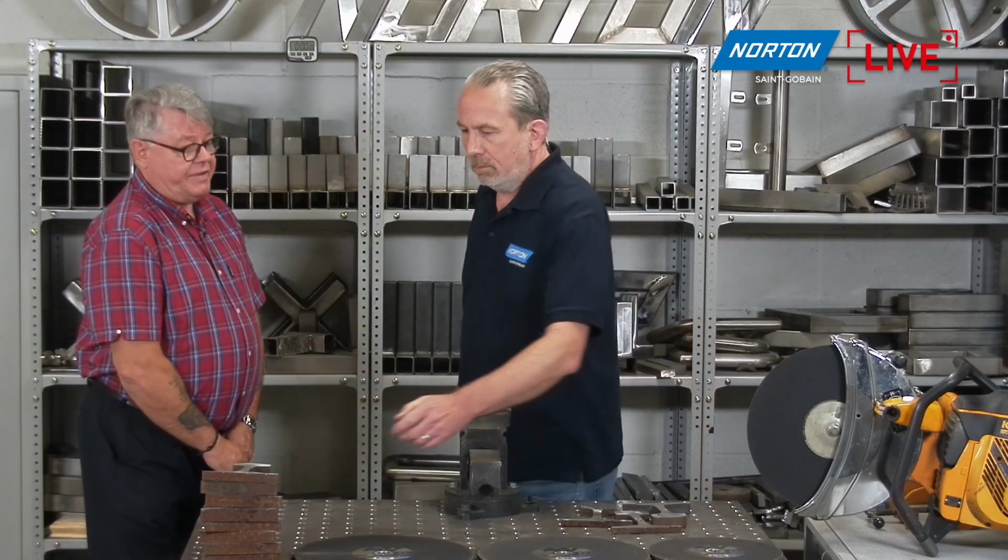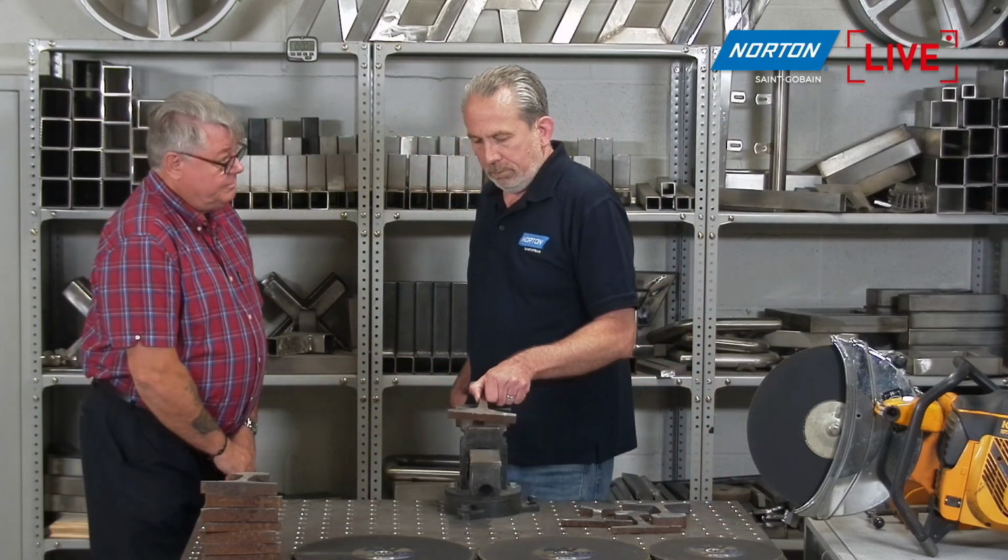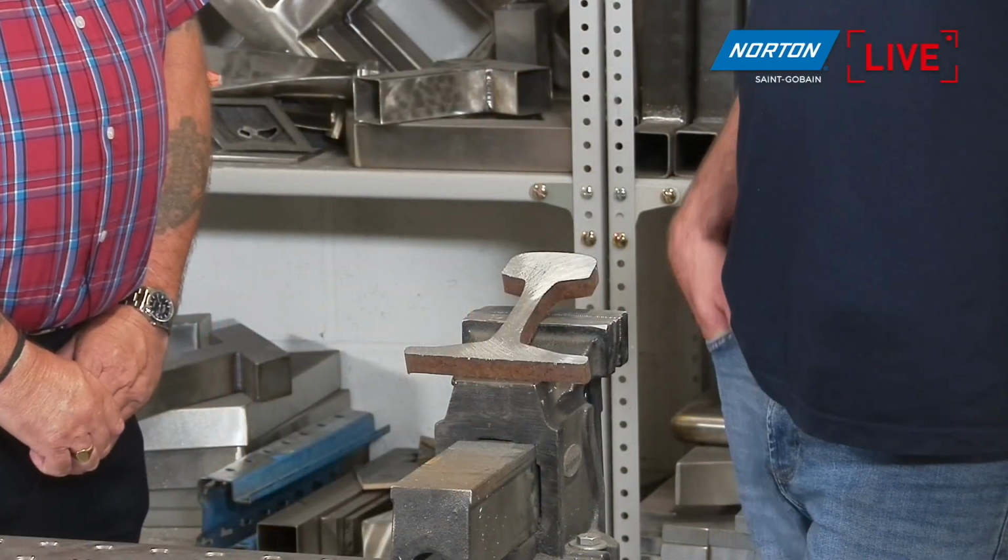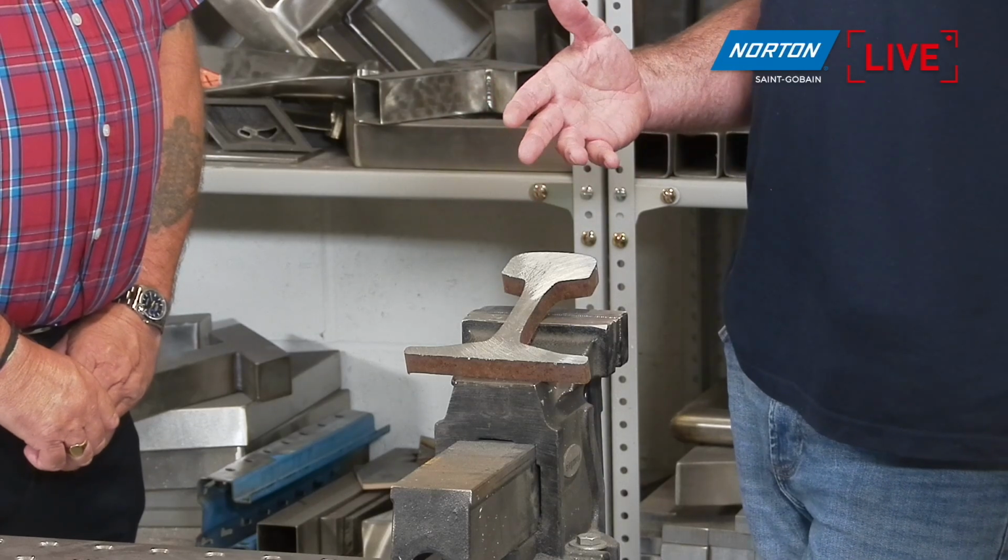So, Ian, again, the rail sections, we've got UIC 54 and UIC 60. Why are there two different types of rail? It's an EU standard, right? Absolutely. These, and worldwide predominantly now. Most railroads, obviously from a cost perspective, for manufacturing the rail sections, they've produced the two. The UIC 60 is the larger rail section, so that's normally used where there's heavy traffic. Okay. So it lasts longer because of the extra size in the rail, and there's a greater time distance between replacement. So it's bigger, more volume of material, so therefore you get greater life out of it.